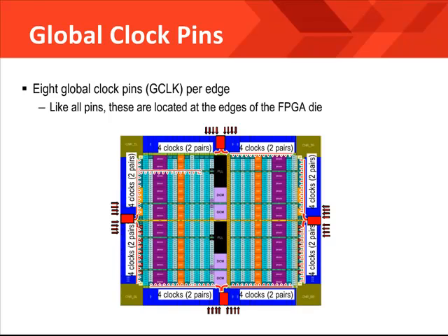Spartan-6 is a wire bond type device. This means that the I/O pins are distributed around the periphery of the die. This implies that each pin is associated with an I/O bank on the perimeter of the device, like the Spartan-3 device family. But unlike Virtex-5 or Virtex-6, which have I/O banks placed in columns throughout the FPGA. This also places some restrictions on clock input pins.